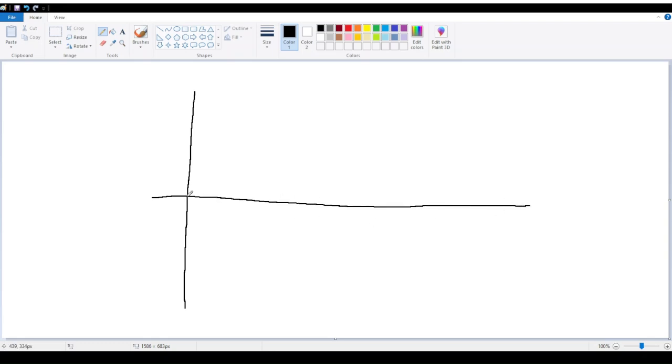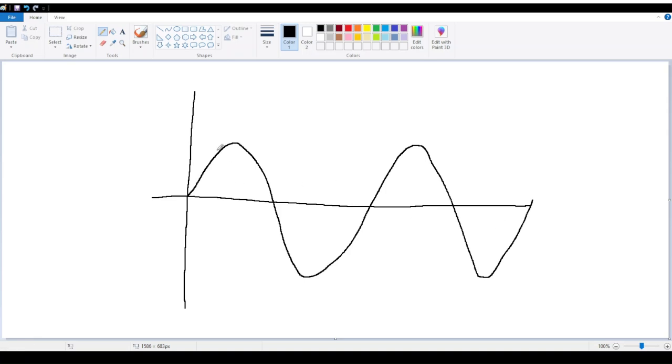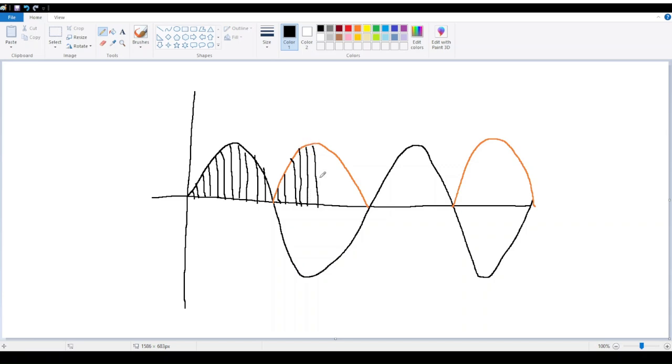All right, so we're dealing with the sinusoid here. Previously, we were detecting the peak. At this point, we're going to have something that looks like a sinusoid. With the closed loop control, at every single point we're going to be comparing, so the reference voltage will keep changing for every point. And as stated previously, we're going to be rectifying it. So this is essentially what we're going to be looking at in the code. We're comparing at every single point over the 20 millisecond cycle, as opposed to just using the peak.